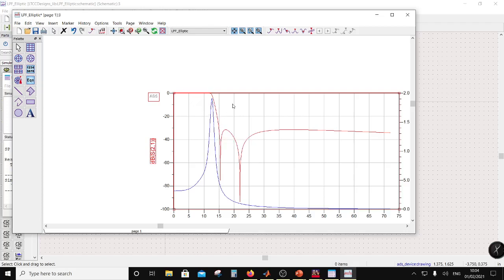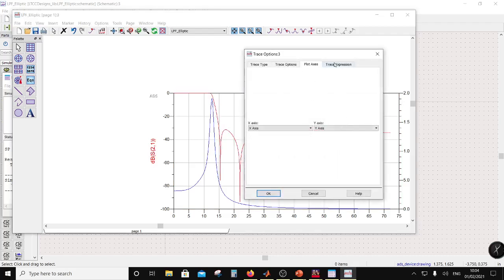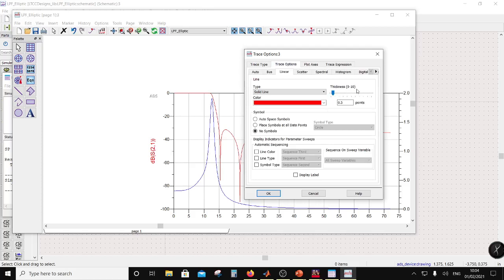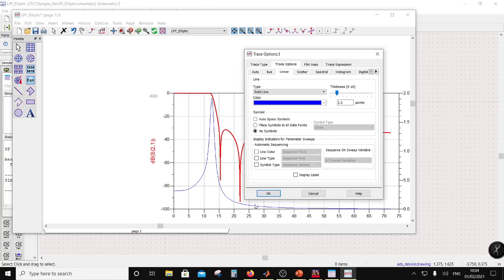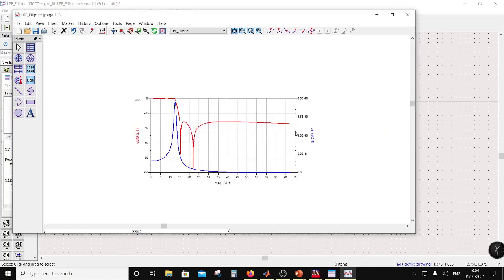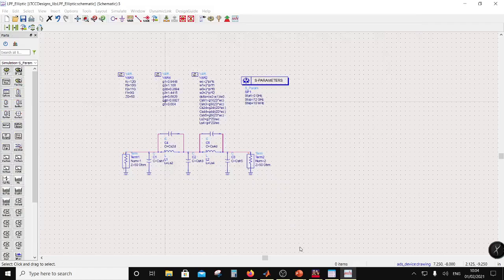Now in this Chebyshev implementation, the book I referred, okay, you can derive different formulas. In one formula you can optimize for this cutoff. In one formula you can optimize for the stop band. In one formula you can optimize for the ripple. So refer to that book to be able to do that. Okay, so this is a low pass. I will do a transformation to high pass.